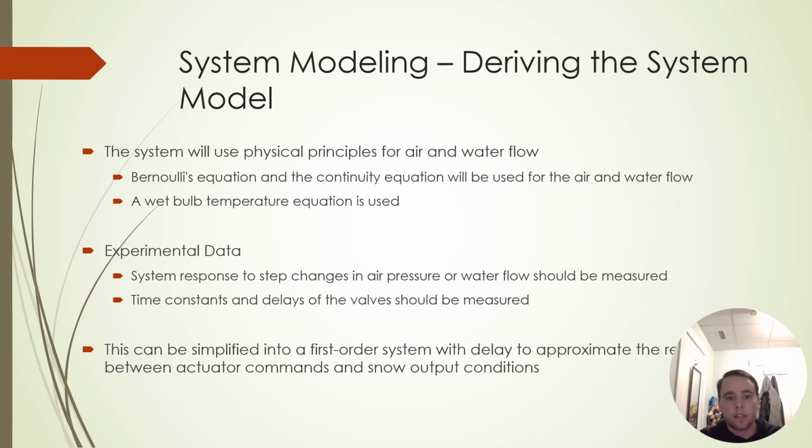Experimental data, so system response to step changes in air pressure or water flow should be measured. And time constants and delays of the valves should also be measured to accurately model the system. This system can be simplified into a first order system with the delay to approximate the